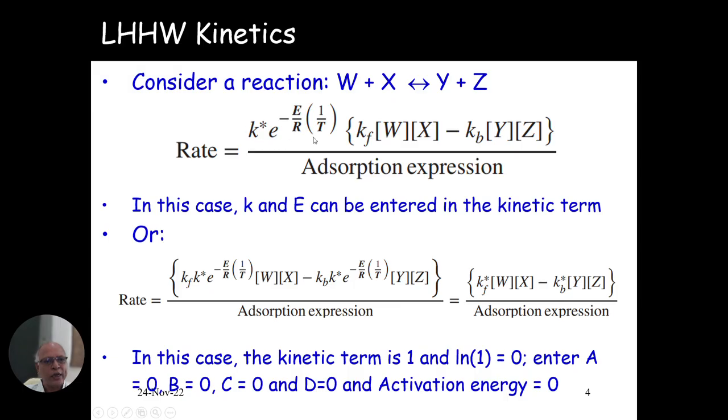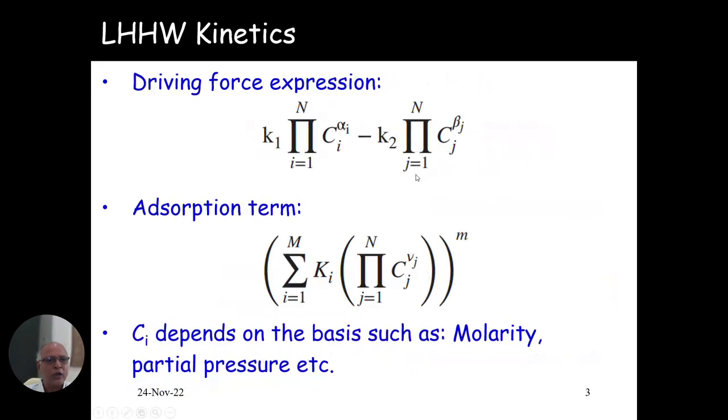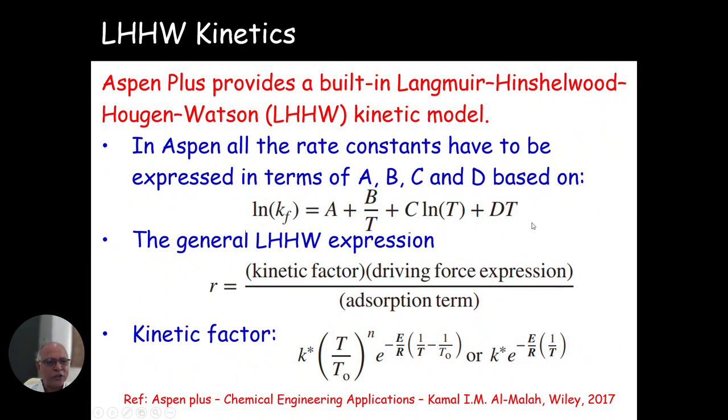So when you are writing this rate law in this form, you will be able to define the kinetic term. When you are defining this kinetic term, you need not take logarithms. Only when you want to represent the constants involved in the driving force and adsorption expression, be careful. This has to be done only with respect to the constants involved in the driving force as well as the adsorption term.